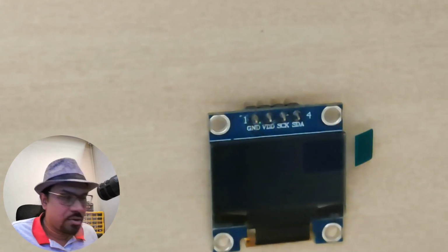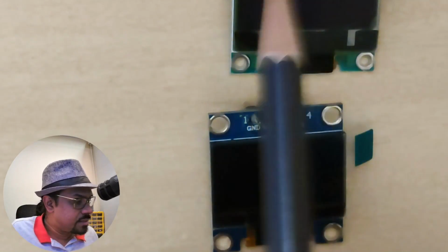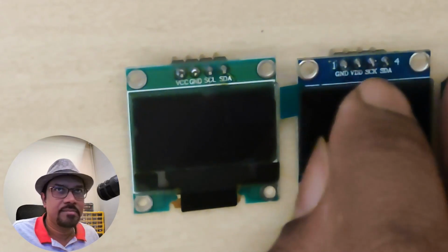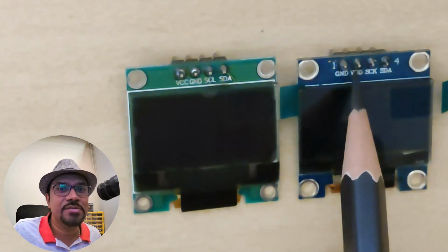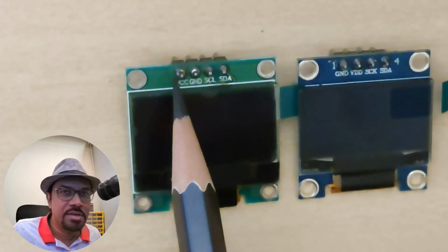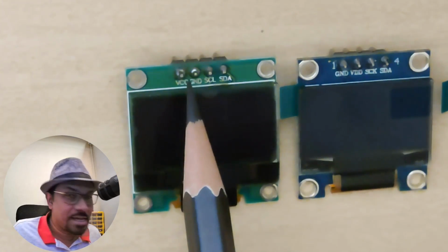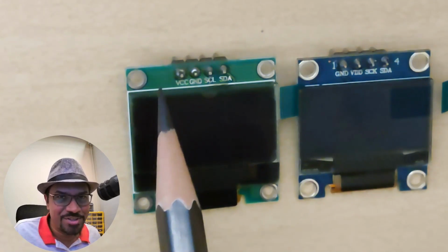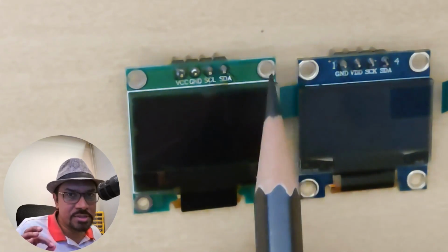You have the same display. I got another one, which is also the same as this. But there's a small difference here. Let me just move this across and keep this side by side so you can see it better. In here, the first pin is ground and the second pin is VDD. However, in this display, you can see that the first pin is actually VCC. It's the same as positive supply. And the second pin is ground. So you have to be a little careful about the pinouts. The pins come in various configurations from what I've seen here. So these are the 4-pin displays which primarily use I2C.